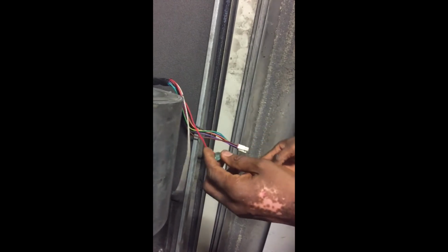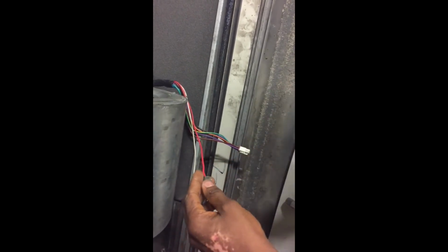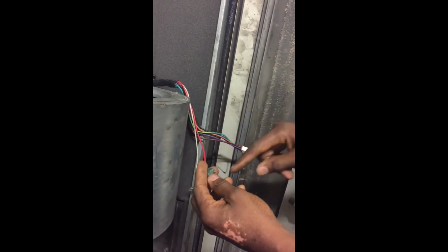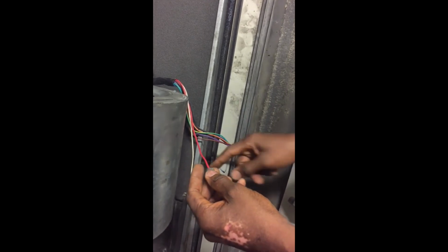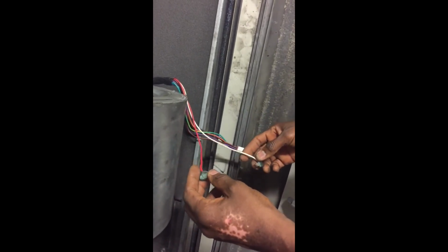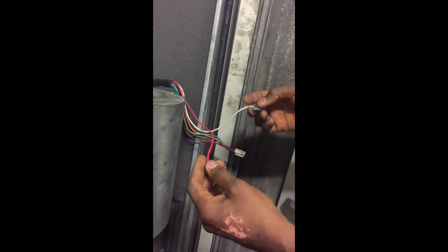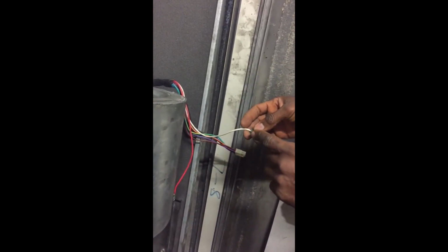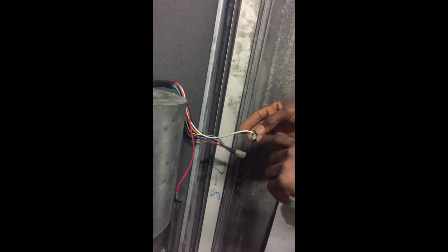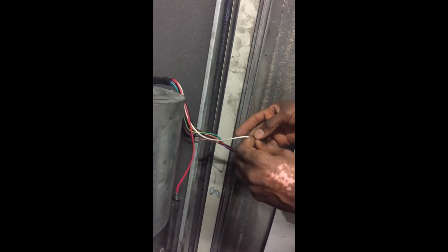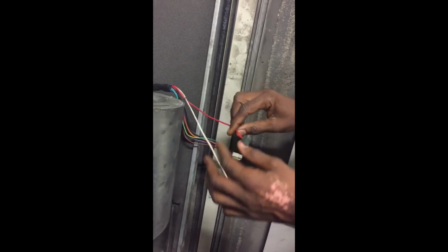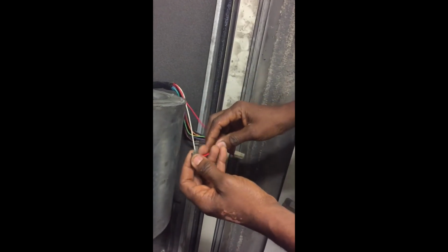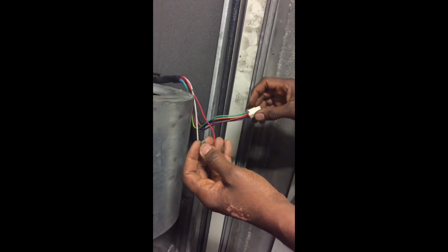For instance, ideally our power supply is supposed to come here. The live is supposed to come here. When the live comes here, the capacitor, which is going to the start terminal, will be connected here, one terminal of the capacitor, and the other terminal is supposed to also make contact with the supply. I want to assume that this has been done inside, but to verify it, we need to know whether this point, which is the run, has continuity to the supply cable.